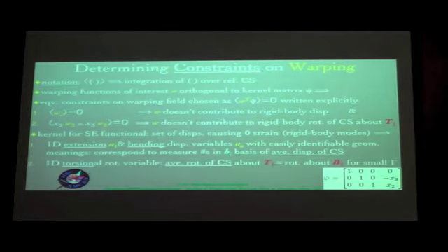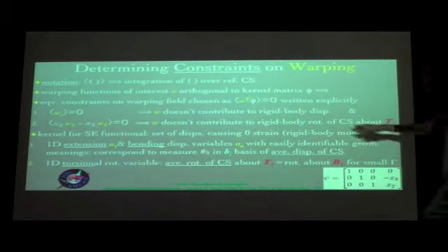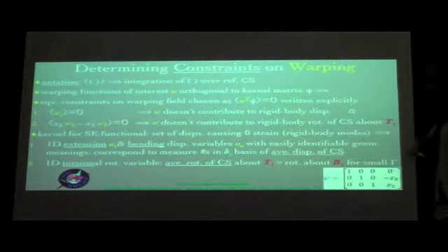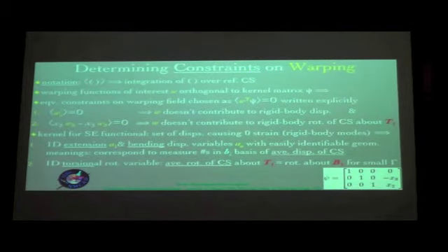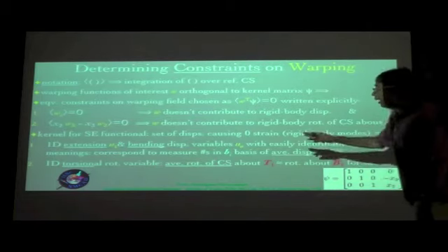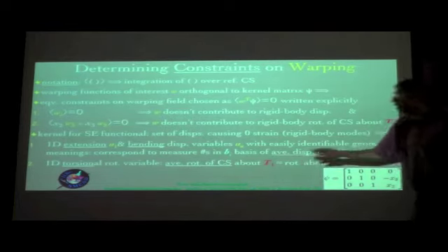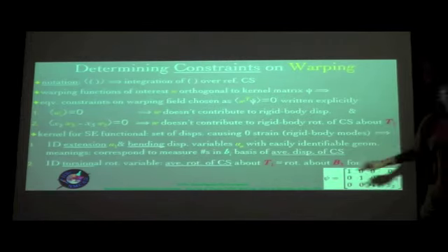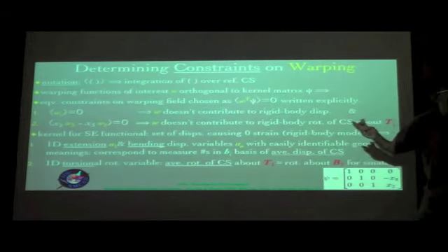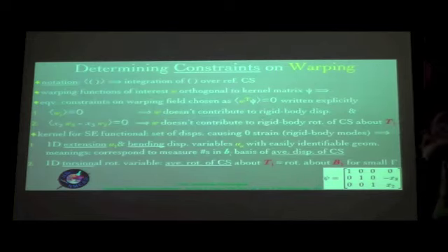The second aspect which is a fallout of this, because of this second set of constraints, in other words the rotation related constraint, is the fact that the 1D torsional rotation variable, the average rotation, is nothing but the average rotation of the cross section about T1, which is approximately equal to the rotation about B1 in the case of small strains, which is what we are dealing with. But that's not an approximation that we are taking, it's just for physically visualizing the meaning of that quantity, whether it is about T1 or B1.